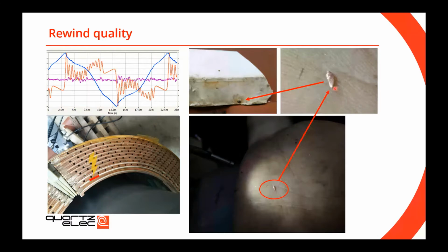And that little alloy broke through the Nomex insulation, causing that interturn fault. It's a good thing that this particular customer had that online system installed. If he didn't have it, most likely he would be running this machine with the fault present, and God knows what would have happened with time. So he was lucky this time.